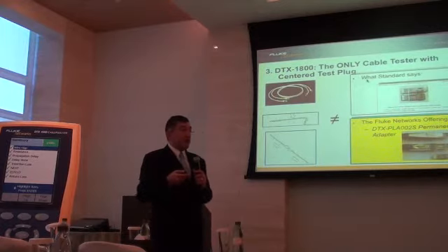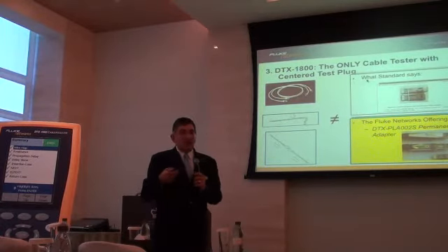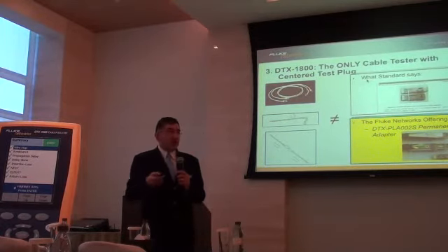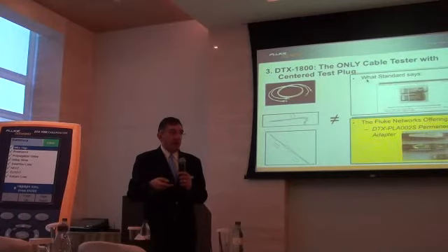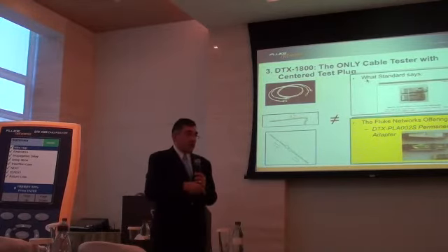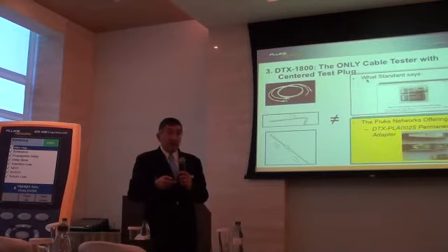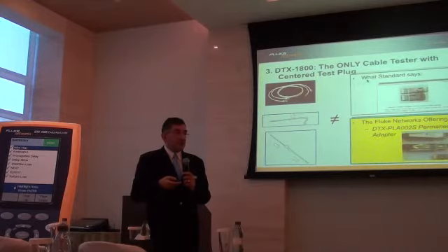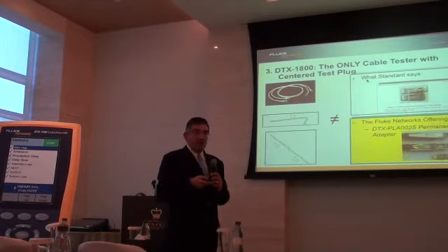First of all, the patch cord performance, you as installers, you want to do that, be my guest, but the issue is that the patch cord performance will degrade with time. So today, if you give a pass on a channel, it doesn't guarantee that tomorrow you will have the same pass for the channel, because you walk on a patch cord, performance changes. But a permanent link, you can guarantee for 25 years. Why? Because it's fixed. It's the permanent part that you do not touch.